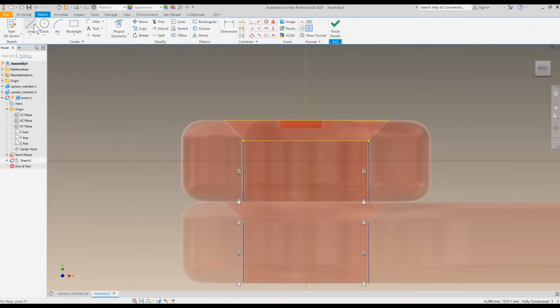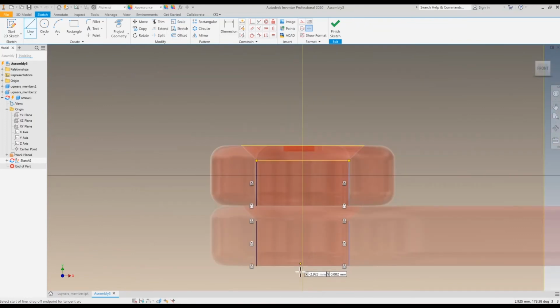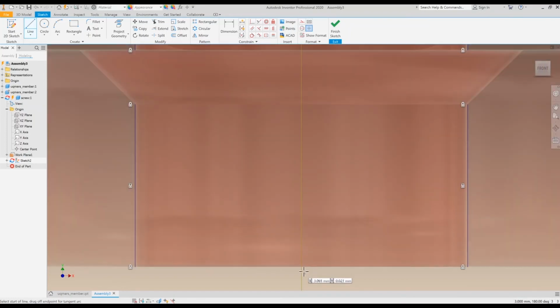That's good. So we're going to use the Revolve tool to do this. So we only need to sketch half of the profile, and then that's going to be rotated about the center axis to give us our whole object. So we're going to sketch off this point here, and then we're just going to make our way around the whole object.